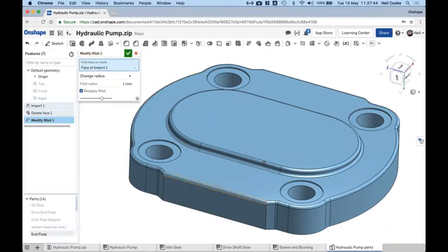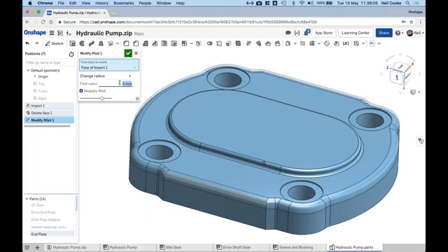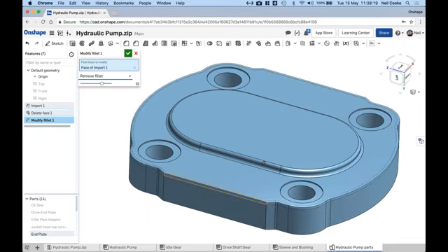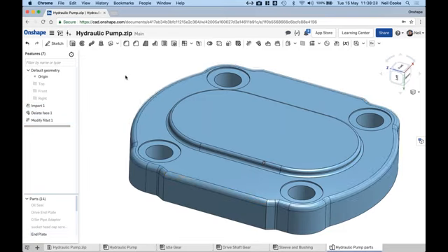What you'll see is when you select a fillet, it automatically tells you the size of that fillet, which is really handy. Sometimes I use it just to measure a fillet. Sometimes if there's no way to physically get a nice rounded edge to measure the radius using the measure tool, the modify fillet command will actually tell you the relative size of that. So you can just go in here and say, change that to 2, 3, 4, whatever, and you can see it's modifying that entire fillet chain. So it does understand, almost in a FeatureWorks-like way, what the changes are. You can change the size, or you can get rid of it completely, and it'll remove it from the entire model. Okay, but we'll leave that on there at 2 mil.